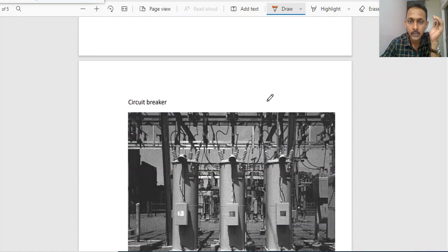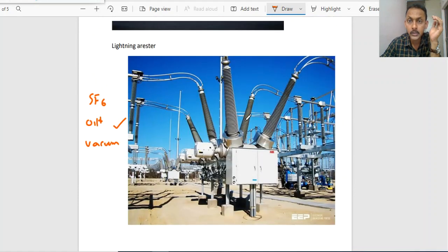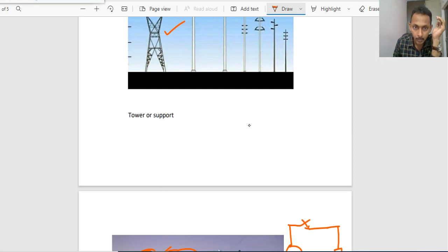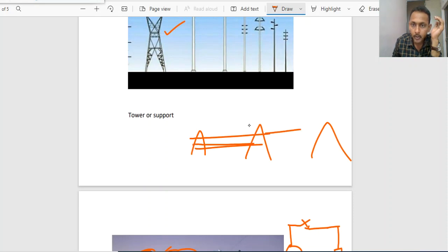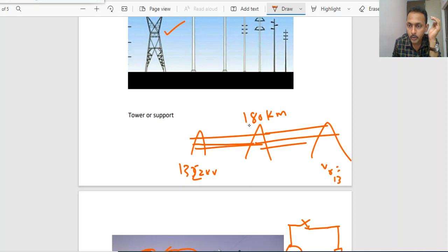Yeah, for switching purposes. And also, once the power is being transmitted over long distances and bulk distances, as I told in the previous videos, it does not mean that if you are sending some 132 kV, after the power is transmitted over some 180 kilometers or some 90 kilometers, at the receiving end also we should get 132 kV. Practically there will be a voltage drop, we can observe, right? But it is very important to maintain the receiving end also at the rated voltage.